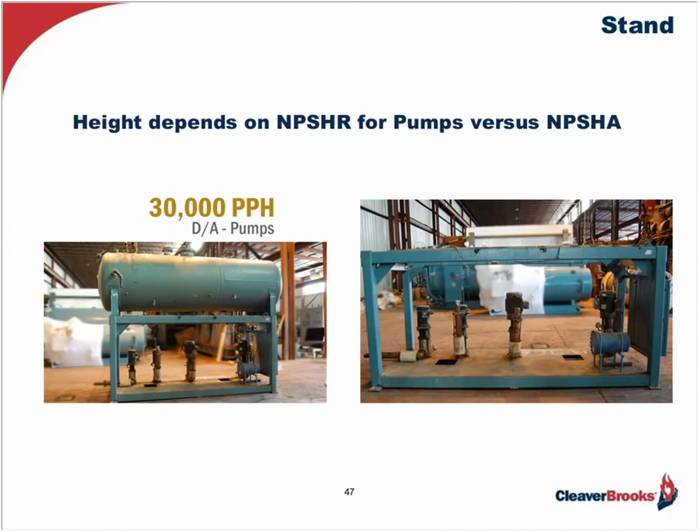We also know what our pumping requirements are with a flow rate of, say, 16 gallons per minute and a TDH of 328 feet. So taking this information, we go to the pump curve example I just showed you before, and find we have an NPSHR requirement of, say, 5 feet, meaning the stand must be constructed to give me a minimum of 5 feet above my pump's inlet center line, measuring from the normal water line in the tank down to the center line of the pump's inlet, and this is to prevent cavitation.